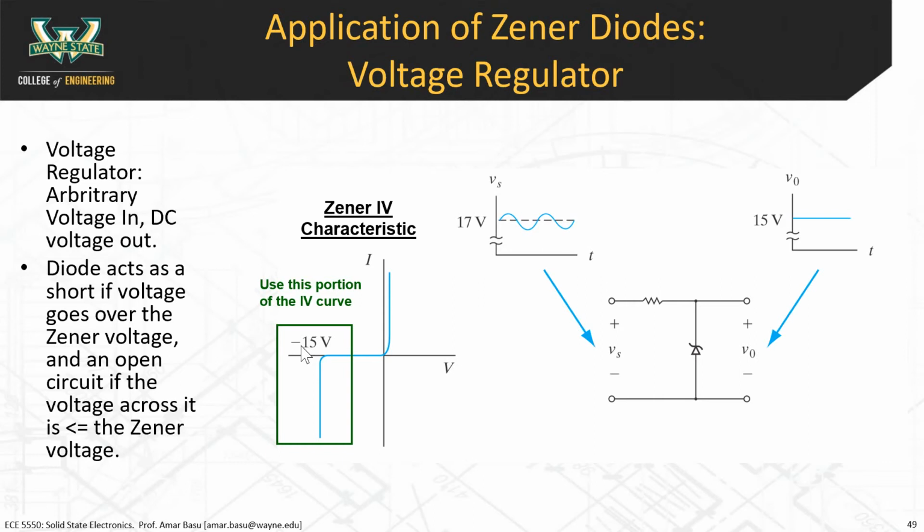So this is why it's important to have a reference voltage. You want to have something in there that, regardless of what's coming in, will give you a fixed voltage coming out, so that you can design your circuit around that fixed reference voltage. How do you make something like that?